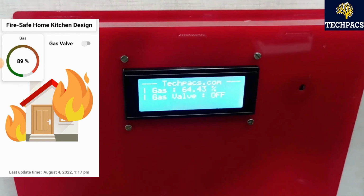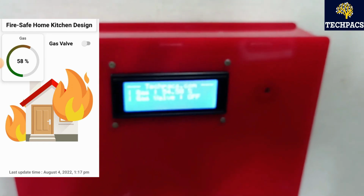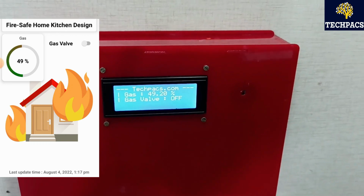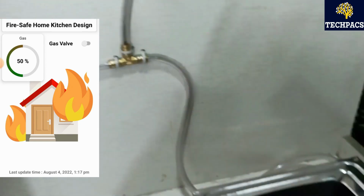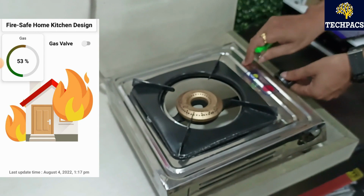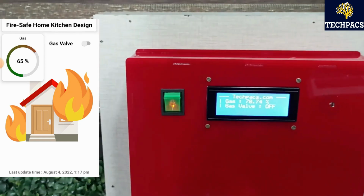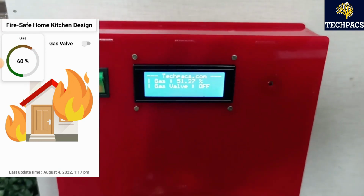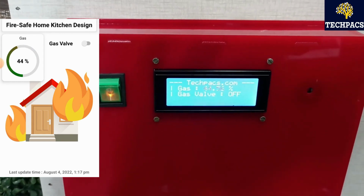And the gas valve automatically turns off, as can be displayed on the control box, and now the percentage of the gas particles can be seen decreasing in the control box. So in this case, even if we turn on the burner, it will not get turned on as the solenoid valve has automatically closed. The percentage of gas particles can be seen here. It is reducing continuously.